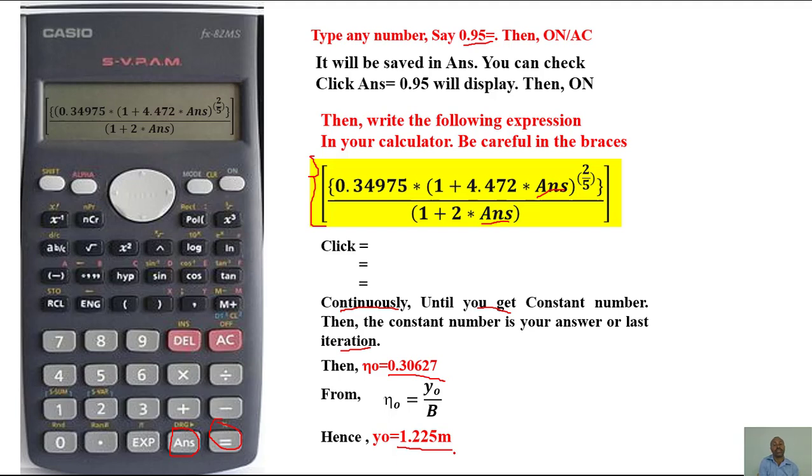bottom dimension. Why does it change? You have the same bed slope, the same bottom dimension and also the same Manning roughness, and the same flow rate. So the main issue is that the trapezoidal channel is just a stretch of the rectangular one, like this. Clear? But the rectangular channel is this one. So due to the stretch, the water level, initially 1.81, but due to the cross-sectional shape of the channel, will drop. So this is the normal depth, 1.225.